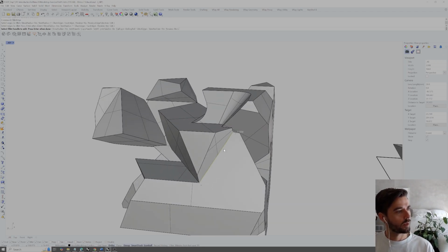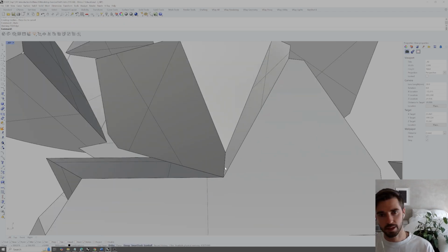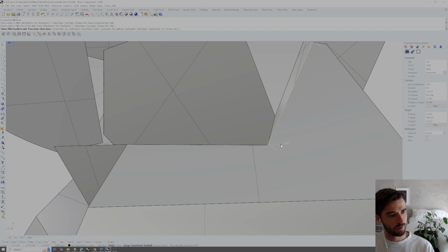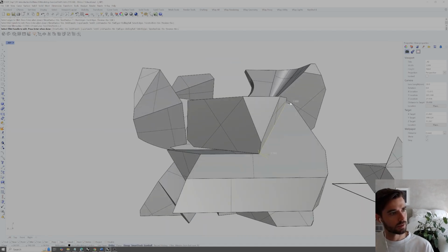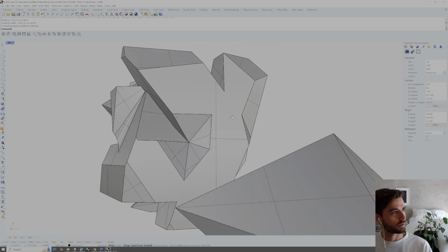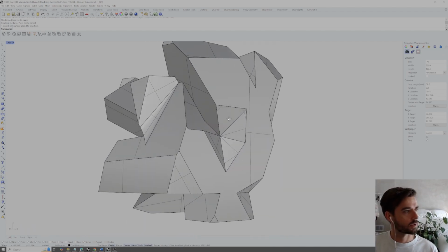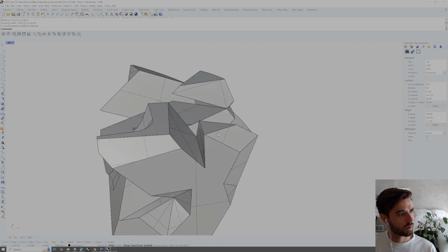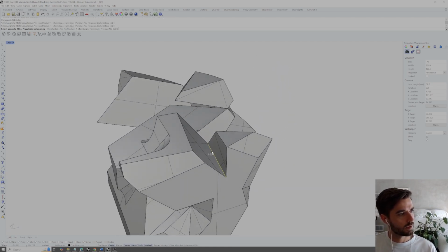And then here, maybe what we'll do is try a 0 radius and then a radius of 4 at the base. It's going to need to be less than this edge length, so we can try that again with 2, which should be less, and then this can be 0. Okay, there we go. So it's still a closed solid polysurface, and we're getting a little bit more of those nice radii in.